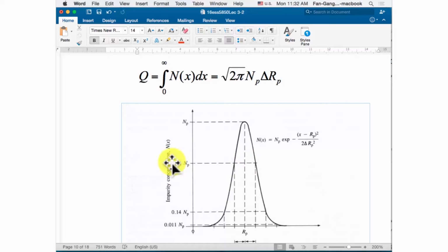And also the control of the dosage is more accurate than diffusion. Yeah. But there are also some downside for implantation. Implantation, because using shotgun to shoot the ions into the material, actually those areas for the ions passing through will cause some damage. Right? It's shotgun. Diffusion is more gentle. Yeah, you're like a thief, stealing into the area. But this is using shotgun, like a robber. You rush into, force into, the area. So it causes some damage.